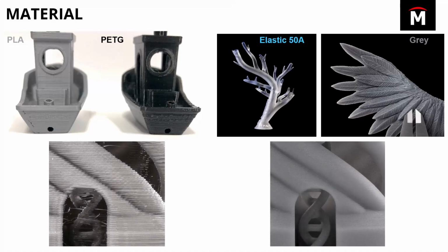Now you can even step further back, and we looked at the different printer technologies. If you needed to print something like I mentioned, like an injection mold, and it needs to capture very intricate details, that's where you might say, well, I need to choose a resin-based material, and that would then in turn push me to a resin-based printer, like an SLA printer. Versus, hey, I just need something a little bit more basic. The surface finish doesn't need to be quite as accurate. I really need to go for something that's very strong. That's where a composite technology like Markforged would do you well.